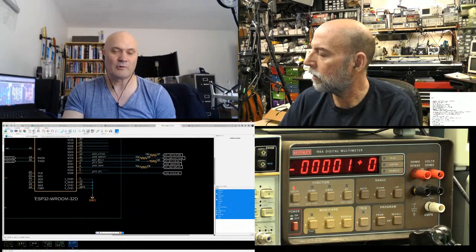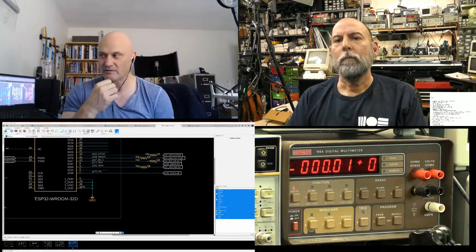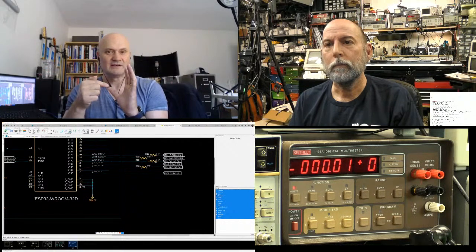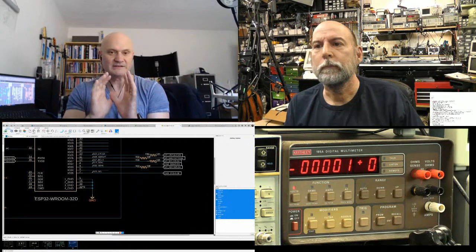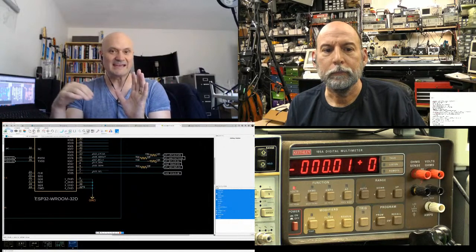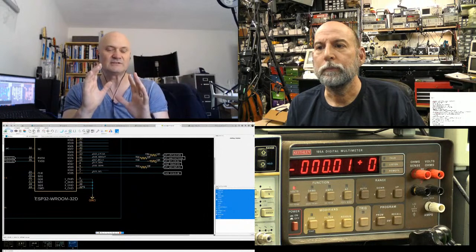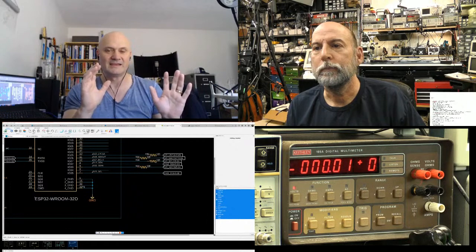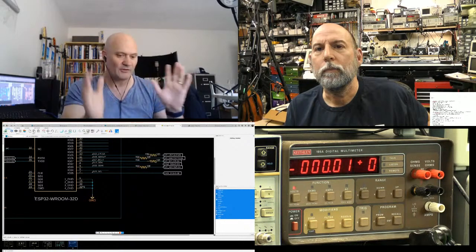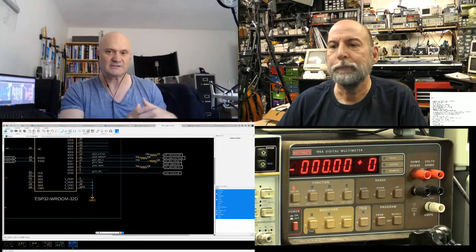I was going to say this is one of the unspoken or maybe fringe benefits of serial transfer between devices on the board, and why I like serial interfaces. You can have a serial receiver that's clocked by an outside device and is completely independent of the rest of your CPU that is a host to that peripheral. Then, asynchronously, the other clock domain, the codec, finishes its transfer, and this peripheral initiates an interrupt, and that interrupt bit flips on its own time. Once that interrupt is flipped, it's locked in, and the received data is clocked through and locked in a register that the CPU can then read and clear at its own leisure on its own clock domain.